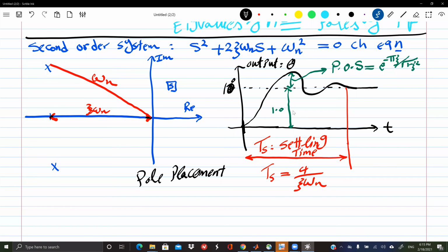And for an important system like an airplane, we will not leave it subjective. So there is a whole area of research. I'm going to take one whole lecture about this. It is the topic of flying qualities. It is based on opinions of pilots for tens of years. We collected the desired locations of the poles that give desired, between quotation marks, desired settling time and overshoot.